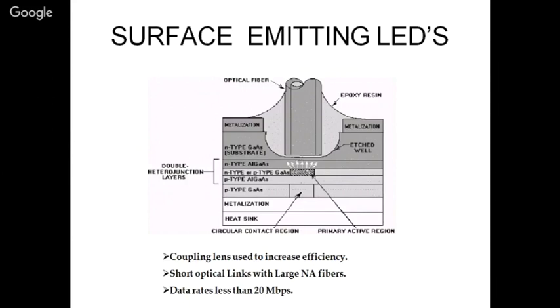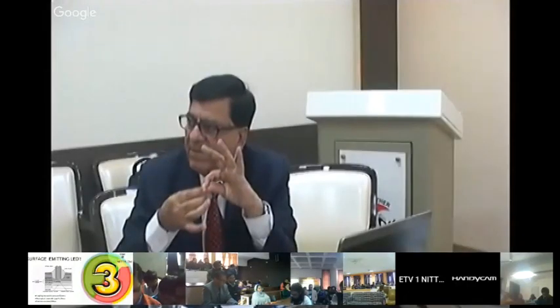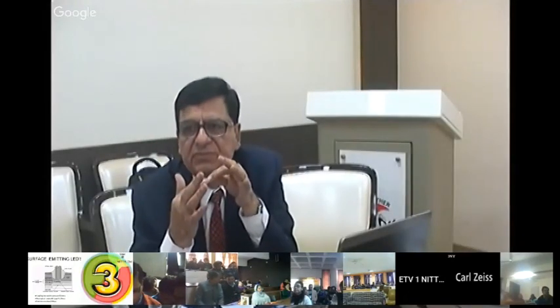So now I give you a device with a pigtail. That is a device from which an optical fiber is also coming, and it is sealed to that. Now what you have to do is only connect this fiber to your spool or to your reel or to your fiber going away. That can be through two connectors, or it can even be fused.